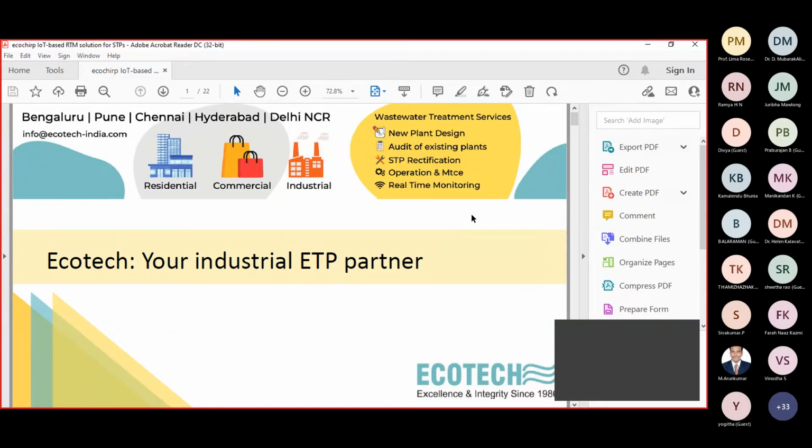Use technologies which will do the treatment most optimally and at least cost. Biological treatment is the least cost method. Next is the physical chemical treatment, and finally the tertiary treatment and advanced tertiary treatment. So you must select these treatment units only in this sequence. Use all the technologies which are conventional, cost effective, and optimal, and then go to the other technology.